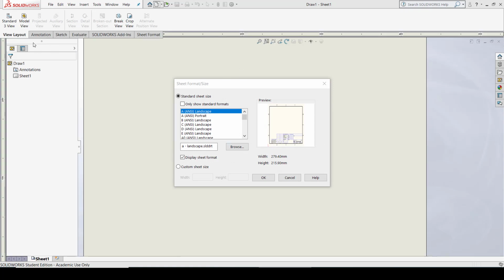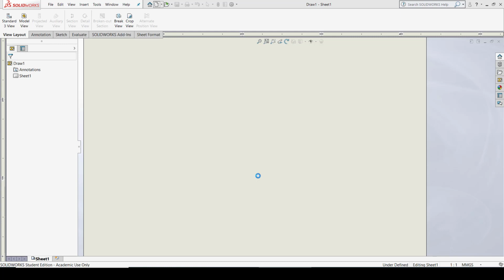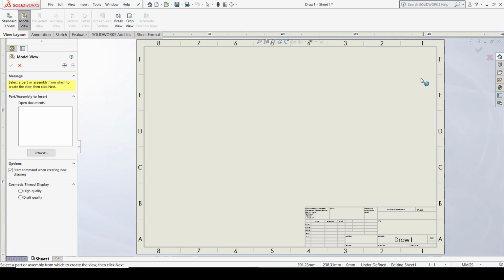As you can see, when you click the drawing module, you are asked about the type of sheet template you require. So we select the A4 landscape ANSI, then I click OK here, or you can select A4 ANSI ISO standards also. It depends upon you which sheet you require. Okay, so I need a landscape A4. You can choose A3 also, you can choose A2 also, no issues. So let us say I select A3, and then click OK here. The sheet format will be A3 right now, and it is ANSI landscape format. Okay, so this is your sheet format.